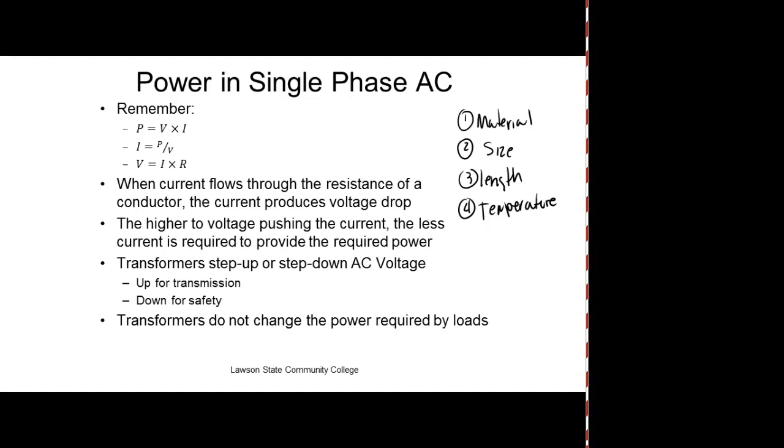And we use that. We have a device called an RTD, which is a resistance temperature device, which is nothing but a big old long piece of wire, and it changes its resistance with temperature. As temperature goes up, its resistance goes up, and temperature down, it goes down. It's a really good, accurate gauge. The only problem the RTD has is it's just real slow to respond. It takes a little while to heat metals up and cool them down, right? So if temperature goes down, the resistance goes down. If temperature goes up, the resistance goes up.